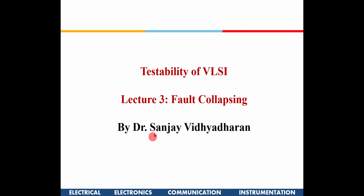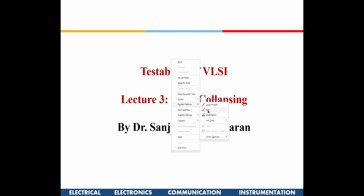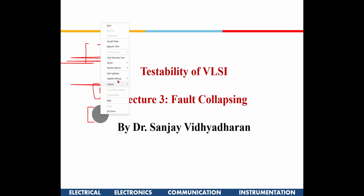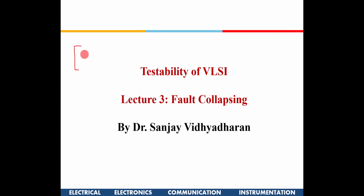So now let's think about what testability is, and how to go about doing testing. First and foremost, make a list of faults in a circuit. Given a circuit, I should run an algorithm and try to list down the faults. So the first step is going to be to make a list of faults. I am giving an overview, and over the next 6 lectures we will see each component. Right now we have just made a list of the faults that we learnt in the last class. Now this list could be very large.